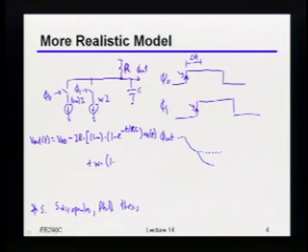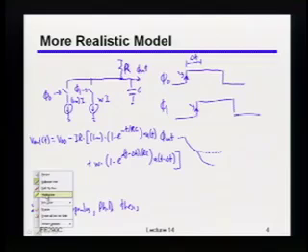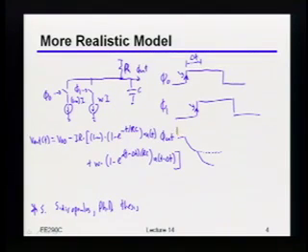Okay, so you do that times 1 minus e to the minus (t minus delta t) over RC, and that whole thing times u of t minus delta t. Okay, and just because there is that sort of impact of the step, that's why I had to keep track of those u of t's and u of t minus delta t's. Okay? So by the way, if you just plot out what we just wrote here, it'll indeed show you something that looks like this. Okay?